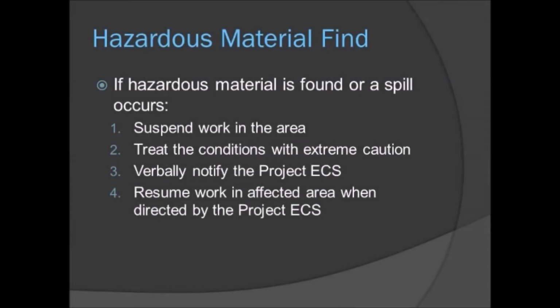If you stumble across hazardous material in the field, the following steps should be followed. Suspend the work in the area, treat the conditions with extreme caution, verbally notify the project ECS. The project ECS will handle all written notification to the UDOT engineer and DEQ. The project ECS will also facilitate the cleanup.